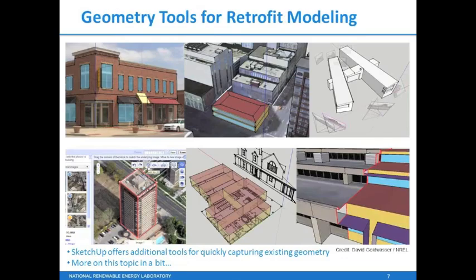Other options for geometry is actually working with photographs. And these photographs can be photographs you took. SketchUp has something called Match Photo that at the top left shows you how to basically trace over a photograph and create a 3D model. This slide here shows that we can import Google Earth content to use adjacent buildings for shading of our model. This here is another, the RSF at NREL. We actually have a third wing now that when I photographed this didn't exist yet, so it's growing.